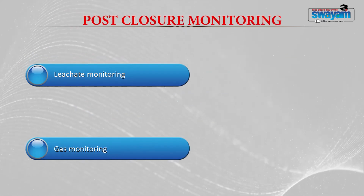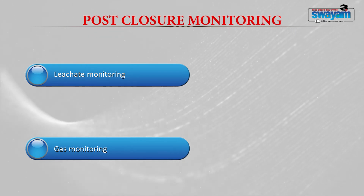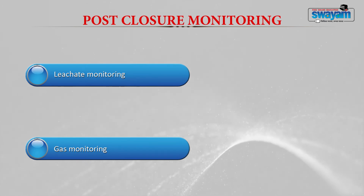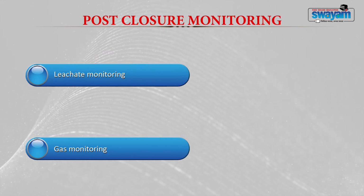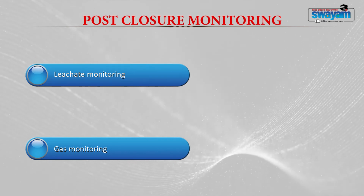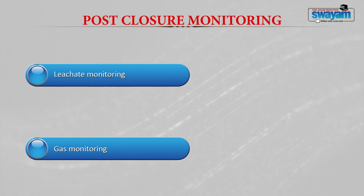Now once the landfill is closed by sealing it with a landfill cover, it is not sufficient to forget about the landfill. You have to do certain post closure monitoring for at least a period of 5 to 10 years. This post closure monitoring is done by leachate monitoring and gas monitoring. Throughout your landfill, you should install, during construction itself, a lot of groundwater wells. These wells should be sealed, and every fortnight or monthly you have to collect water from these wells and analyze it to check the water quality.